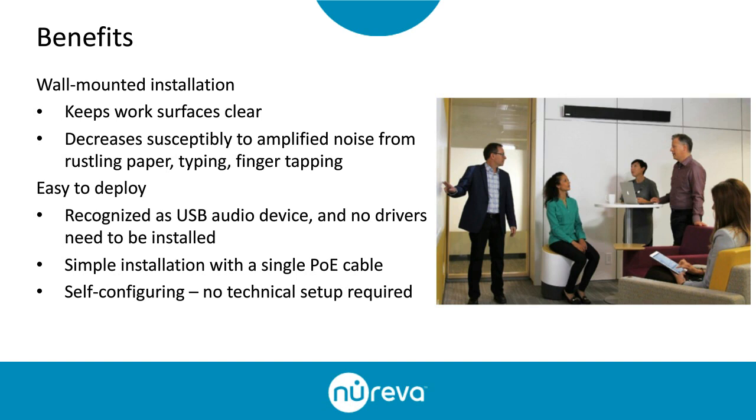And I think the other thing that you noted earlier, and I want to emphasize, because sometimes as communications people we don't really think about this, is the ability to power the unit from a simple Ethernet cable. That single PoE cable connection to the unit is a great benefit, because it allows you to run a wire through the plenum without all the issues of having a conduit, et cetera, that you typically have for power. Installing power is typically a fairly major activity. So again, this goes down to that ease of installation.